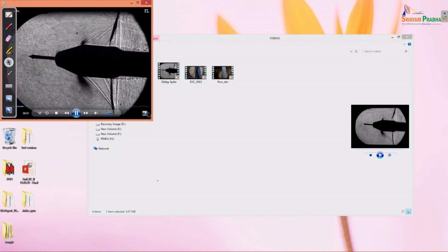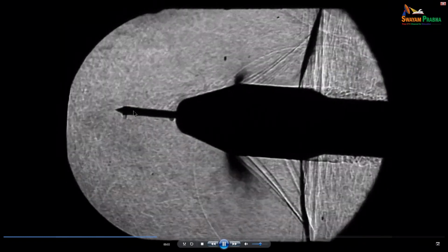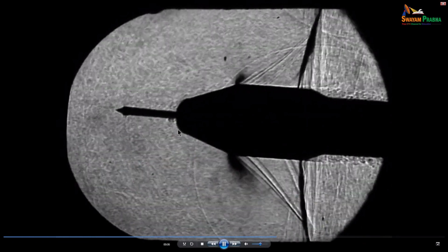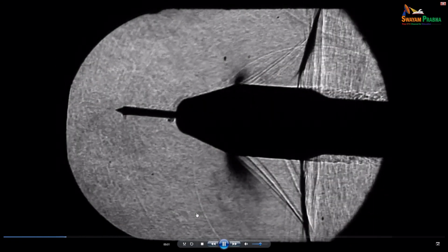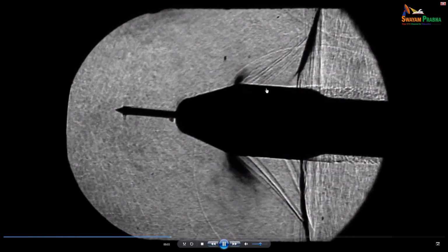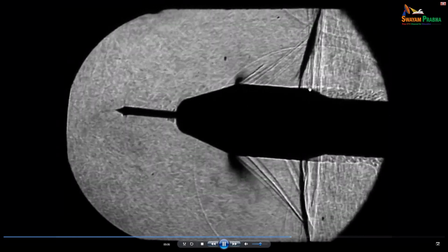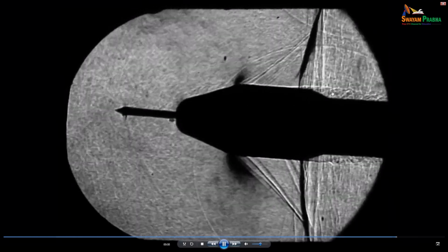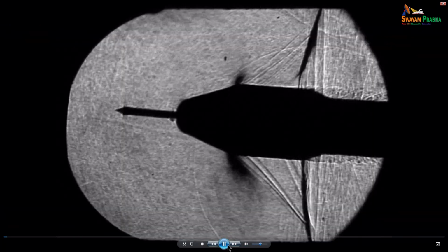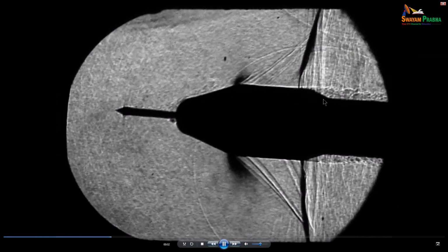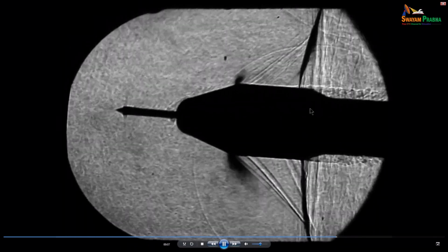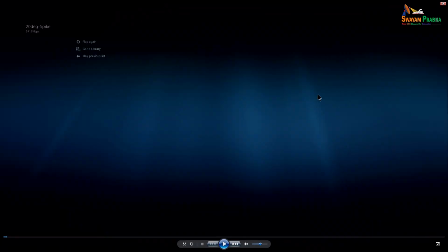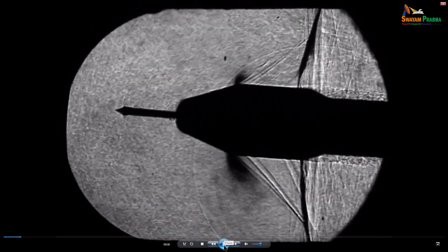Now, that same body, I now have with a spike. This is very interesting. The same body is in a Mach 0.85 flow. What you basically see is that we have lost that tail, and this is a little more stable. There is a flow which is quite unruly, so to speak, towards the end of this whole body, near the neck. It's restricted to that, unlike in the previous case.